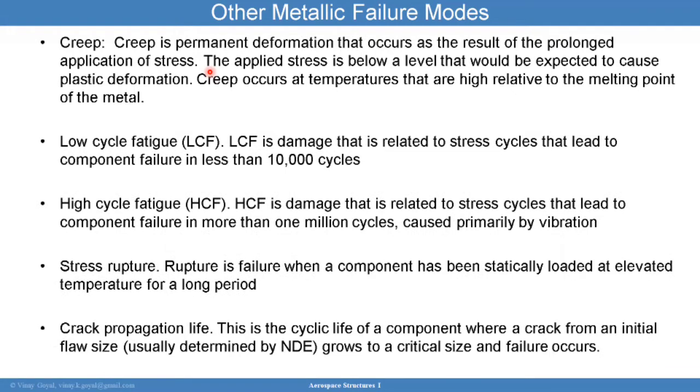Creep is permanent deformation that occurs as a result of prolonged application of stress. So you have this part, and the part has loading conditions applied for a long period of time, and temperature usually makes it worse. That applied stress is below a level that you would expect to cause plastic deformation. Creep will occur also at temperatures, like I said, that are high relative to the melting point of the material.